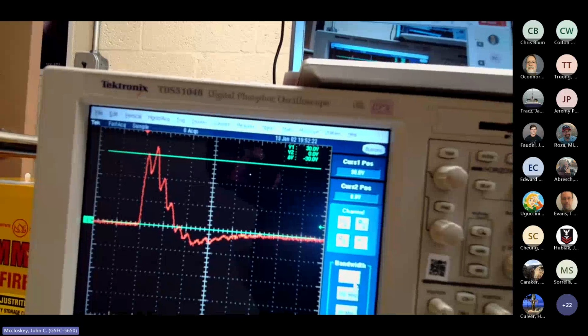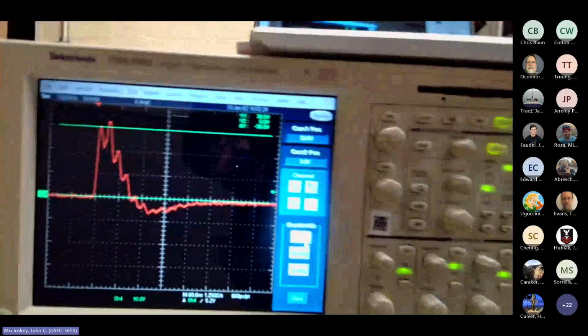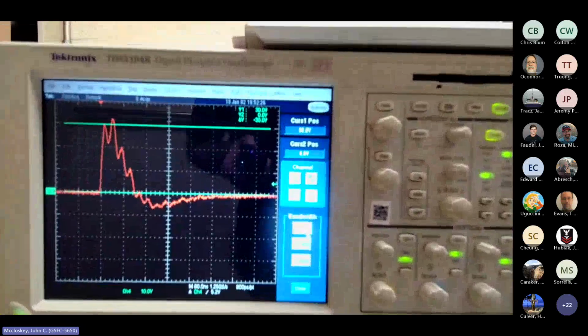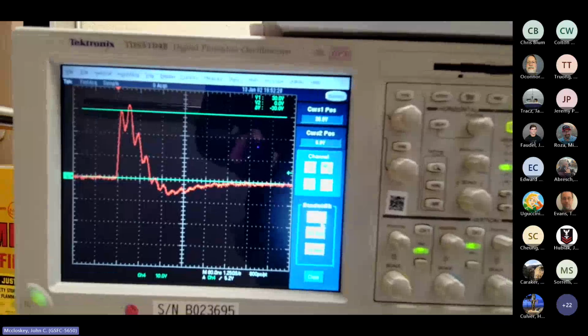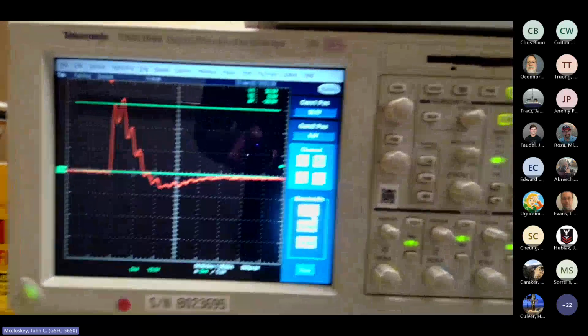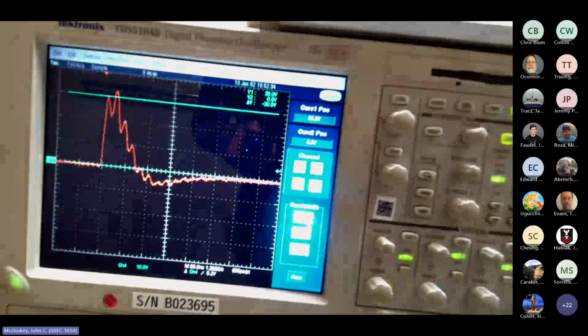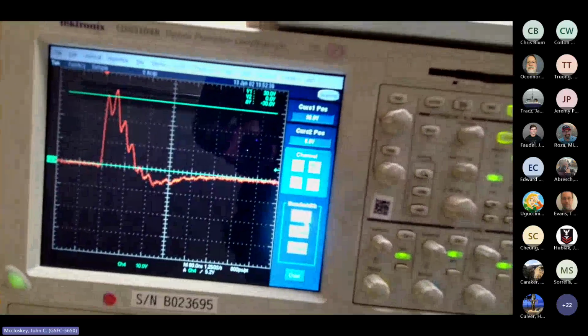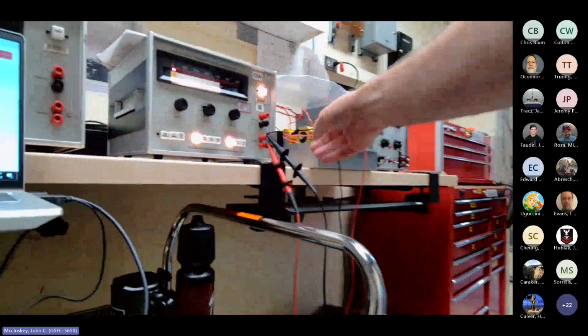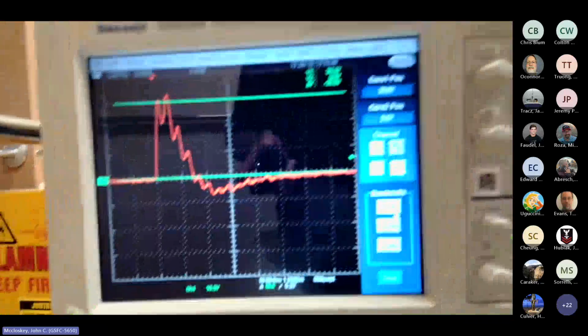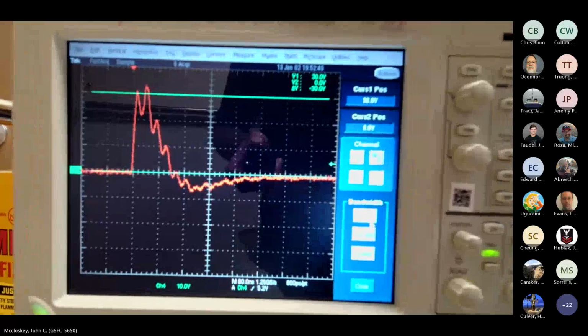Given a choice between a slight under test or a slight over test, I'm always going to go with a slight over test. I want to know that I've actually stimulated the equipment properly, so that there's no question about it. So anyway, I'd be inclined to get a screen capture of this, take a picture of how I did it, into this resistive load plugged directly into the generator.